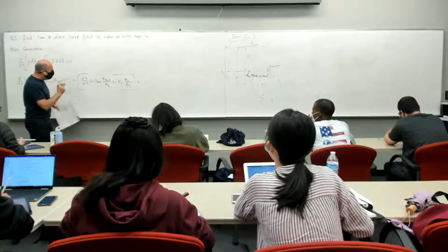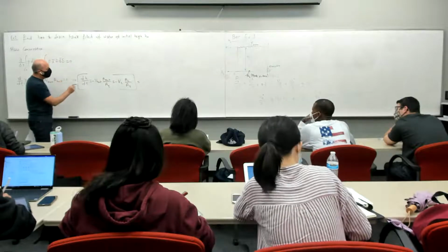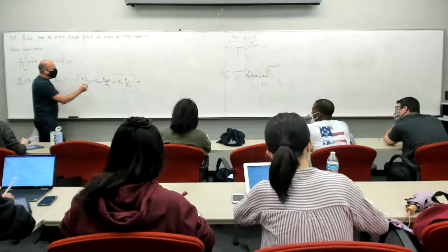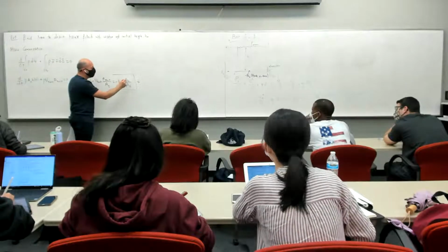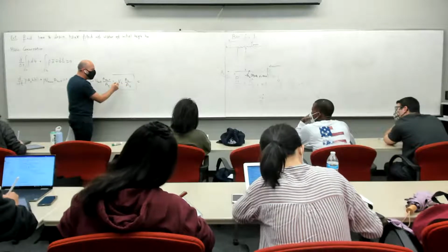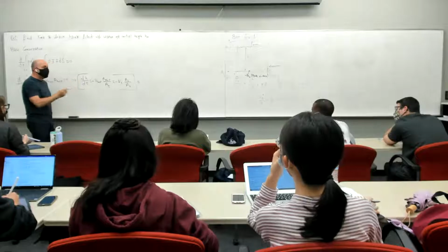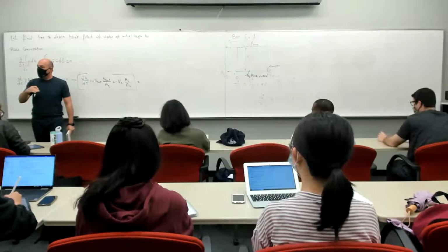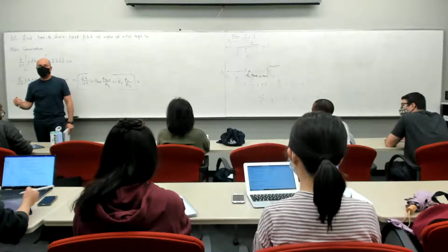Now, think about this a little bit. Again, I repeat what I said when we did this problem in mass conservation. This is the rate of change of the height in time. On the right-hand side, you have a negative quantity, because V2 is positive, A2 is positive, A tank is positive. There's a negative sign, so this whole thing is negative. And therefore dH by dt is decreasing. The negative slope makes sense because the height is decreasing.